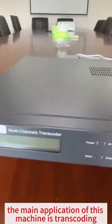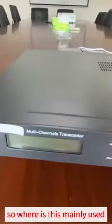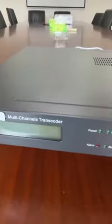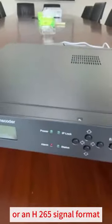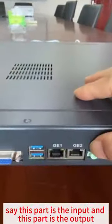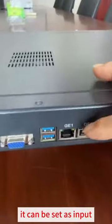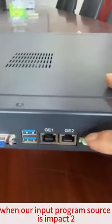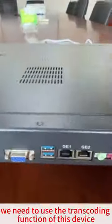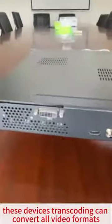The main application of this machine is transcoding. Transcoding means converting between different formats. So where is this mainly used? For example, if we need a H.264 signal format or an H.265 signal format, but our program source, say this part is the input and this part is the output, which can of course be customized. It can be set as input when our input program source is MPEG-2, and we need to convert it to H.264 or H.265. Then we need to use the transcoding function of this device. This device's transcoding can convert all video formats.